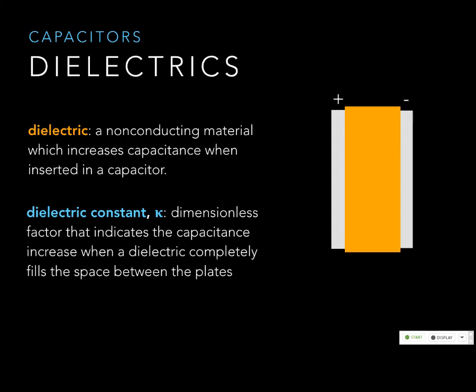So if you have this going on, and this thing discharges, it's discharging straight through whatever that medium is? No, usually when you're discharging a capacitor, you're connecting a wire from here to here. And if you're touching it, then it's discharging through you. That's why you don't want to touch them, because it's really hard for the charge to go this way, so it goes any other way. If you put a wire across the plates, or if you put your hand on both plates, that's when you're going to have a problem like that.